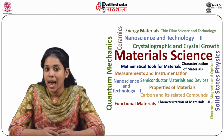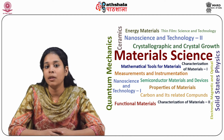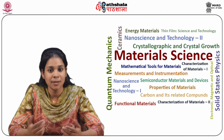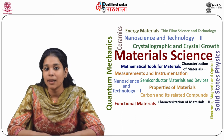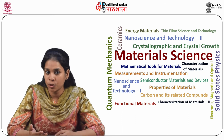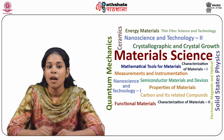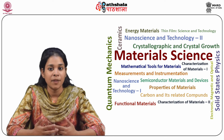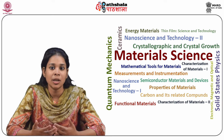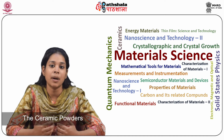The piston and the mold have to be made of a material capable of withstanding stresses at high temperatures. In this case, graphite is the most used material for this purpose because of its high strength, which increases with temperature, and graphite can be easily machined and does not react with the ceramic powders.